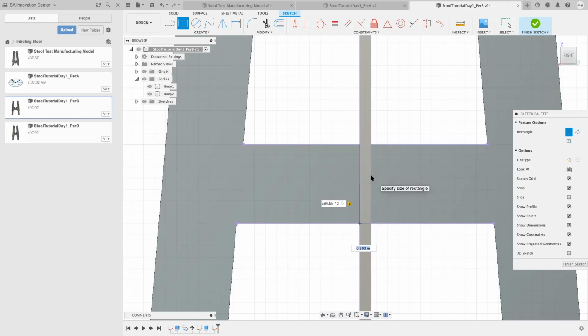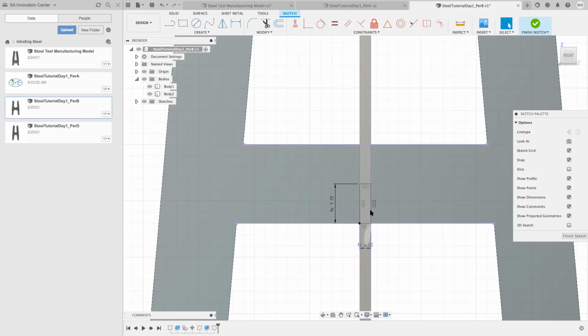Oh, when you hit tab, that lets you jump from box to box, the tab button on your keyboard. So whether I typed in that box or not, I could always hit tab. Some people were asking me, how do I go to a box without filling in one of the boxes? Tab is the way to do it. So material thickness, and hit enter, and now I have my sketch exactly where I need it to be. Finish the sketch.